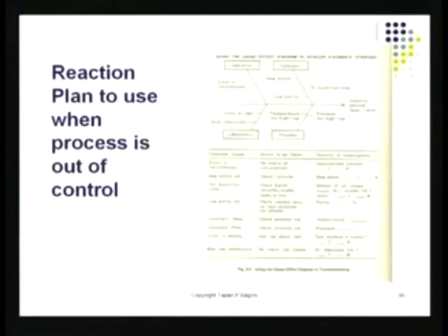Now say you have found a point beyond control limits. Stop the process. Pull out your checklist, and your checklist is this. And very systematically go over the items, and I've listed them out here. So you notice the factors here, the causes that might have caused, in this case, impurity to go beyond specification limits.